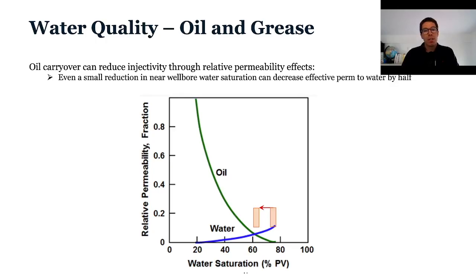Then there is the impact, of course, on relative permeabilities when you have oil residual into the water. So that can just decrease your effective permeability to water and build pressure, but for the wrong reasons, I would say. It's just because you can't propagate efficiently your fluid. So it's very important to get the water quality under control. And here I'm not mentioning oxygen, which impacts the polymer solution. I'm just mentioning, I would say, what's even important during water injection.